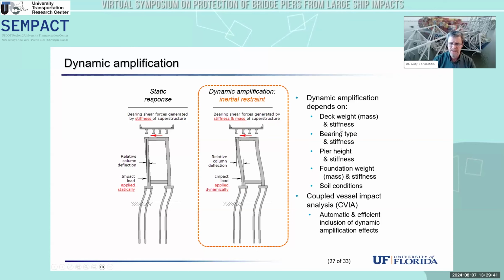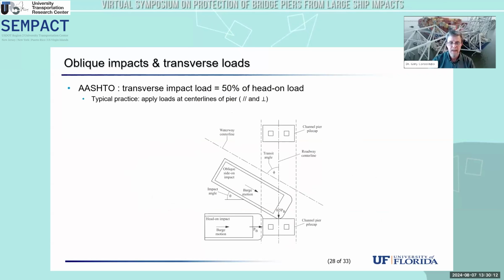It depends on the weight and stiffness of the superstructure, the types of bearings that are used, the stiffness of the pier, foundation weight if you have a large waterline pile cap, and importantly, soil conditions as well. So capturing that accurately with empirical expressions is relatively challenging, but capturing that accurately with a relatively simple coupled vessel impact analysis is a very manageable process, even within the context of analysis tools that are used in routine design. So that's